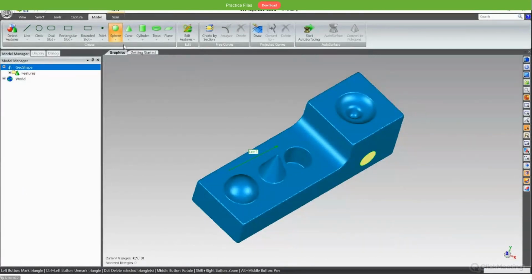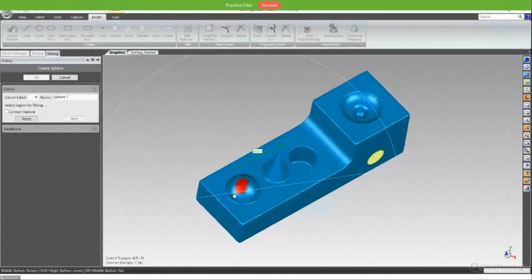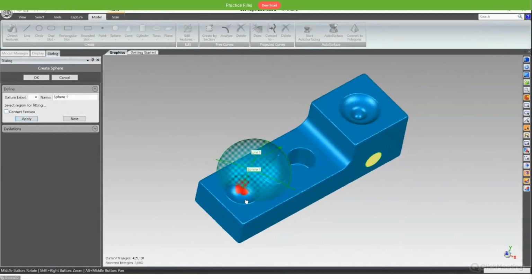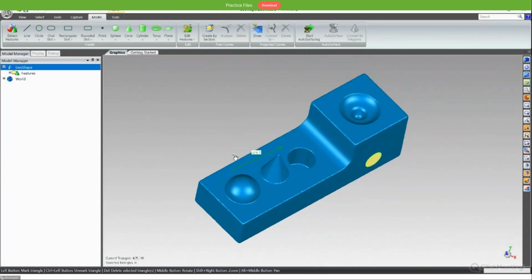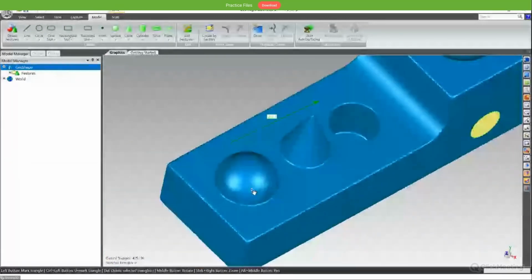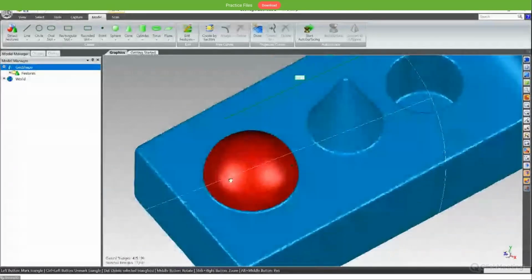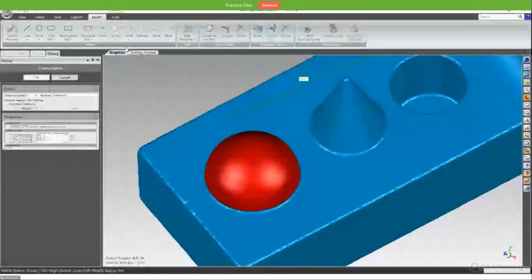Also here, for a sphere, you can do best fit, something like this. You use a brush tool to paint some area of the sphere and then create, oh, it's not good. Okay, cancel. I think maybe using the create angle tool will be much more helpful for the sphere best fit. Okay, here, the sphere has been selected and run the best fit.